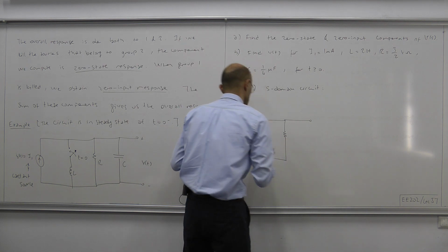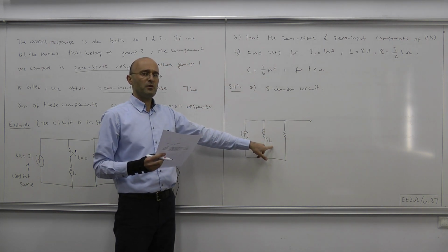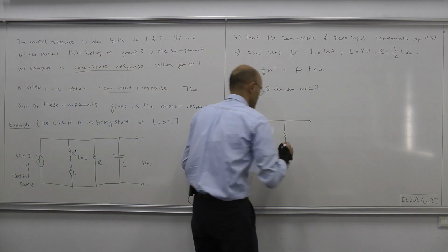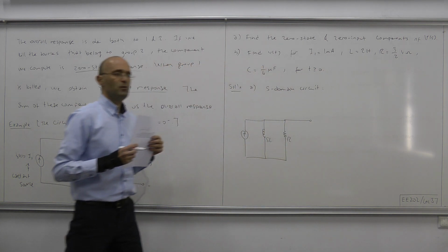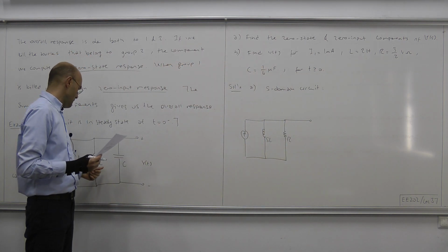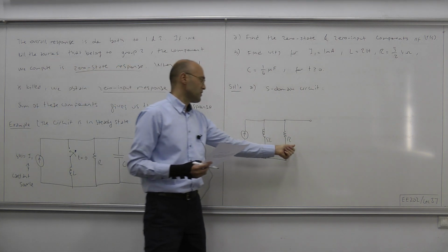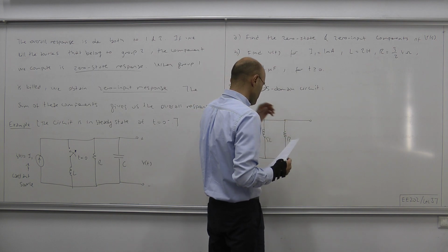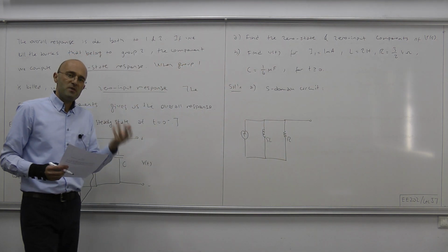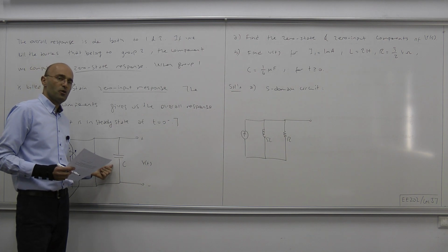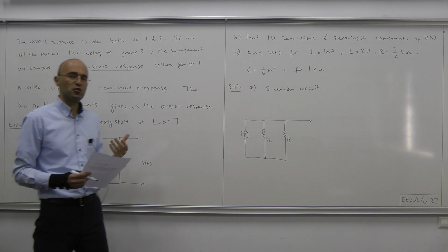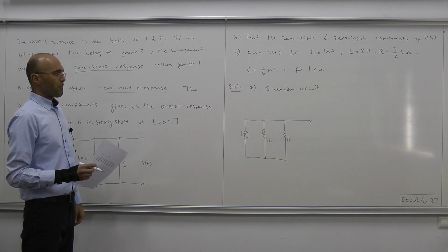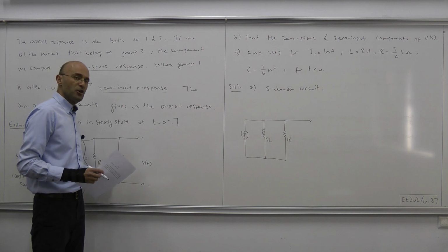And the impedance, so it's only represented by its impedance, and we know that that impedance is S times the inductance, SL. And then as for the resistor, we directly carry it to S domain. Resistance here is R, therefore resistance here is R. And as for the capacitor, it will be represented by its impedance plus, because it has non-zero initial condition, an independent source, a voltage source or a current source that represents its initial condition.